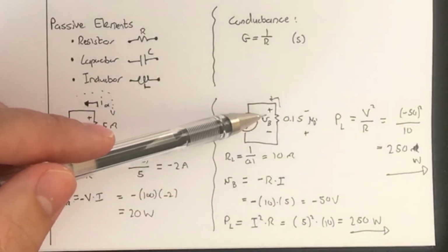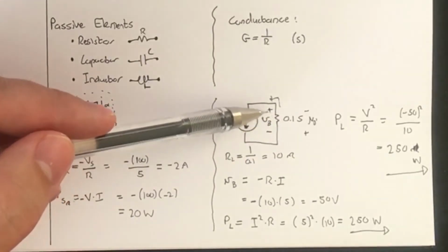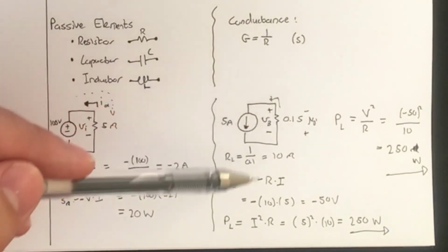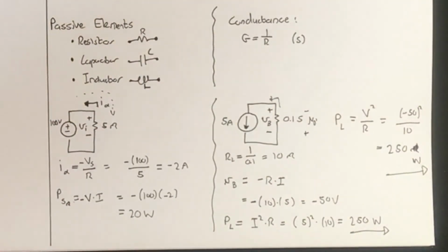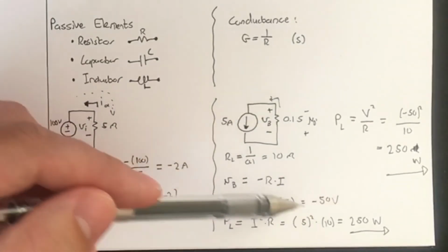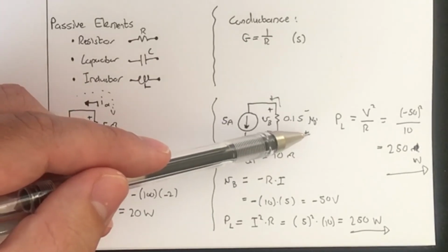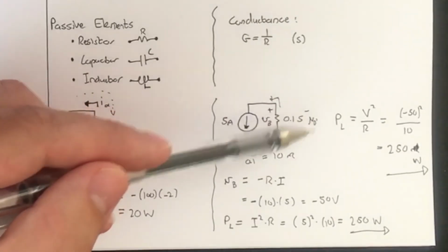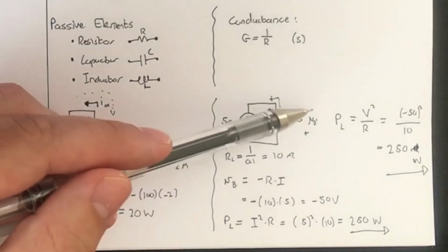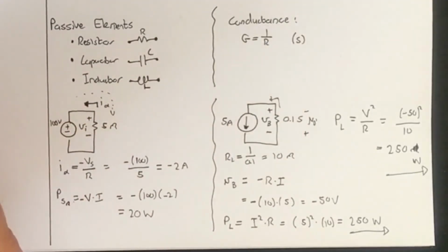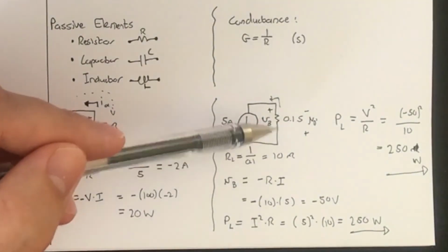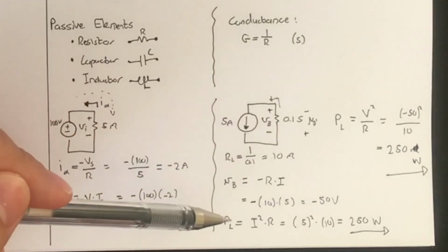So essentially what happens here, again, is that we've just put our terminals on the wrong side. It's not wrong, it's just that we need to stick to this convention, so we will get negative here. If we had defined VB as positive here, negative there, this is VB prime, then this value would have been positive 50 volts, because the current is flowing in to this resistance value.